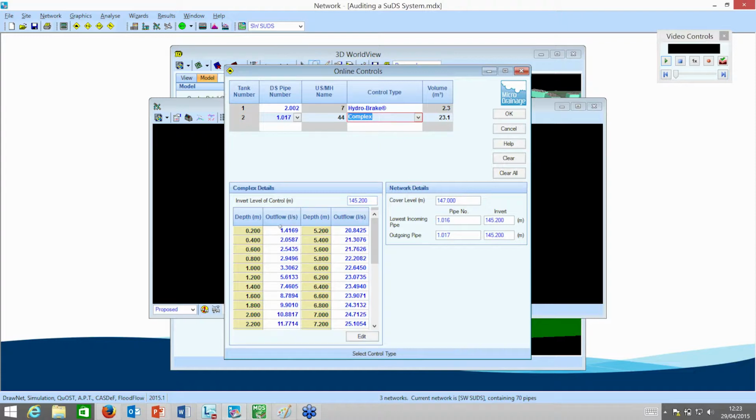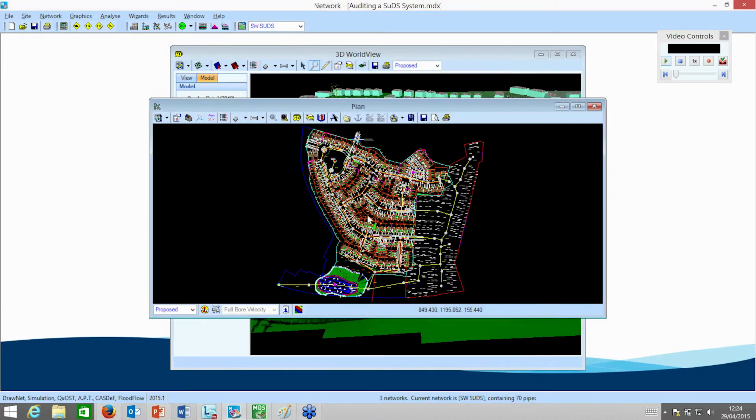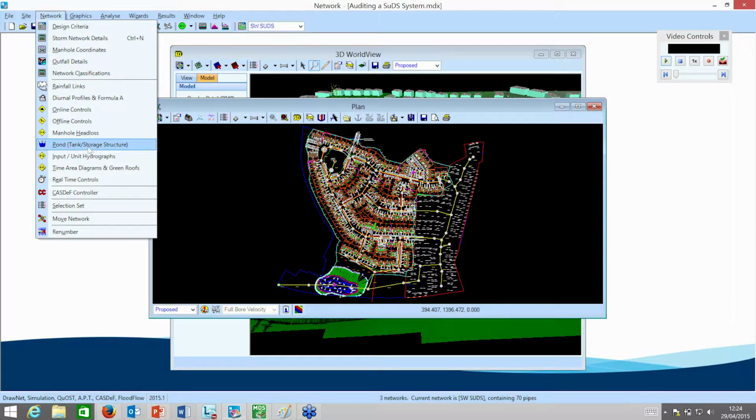And we can see here, based on the depth of water within the flow control chamber, what the discharge rates will be. So that's giving you an indication that there's a relatively free draining soil. We're not in clay. We're looking at hitting those 3 figures. So we're feeling pretty confident that we're going to end up with the same volume of runoff or less, to enable us to be provided with the higher discharge rates, rather than being restricted just to the Q bar figure.